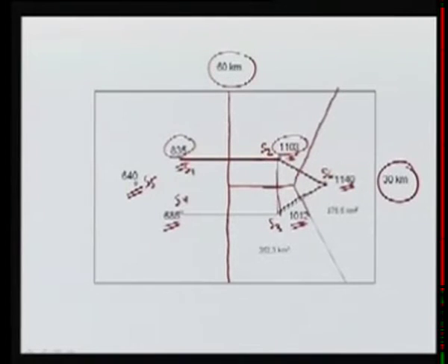Now once we do this, the effective area for the gauge S6 will be all this area, because in this area any point we take, suppose I take a point here, it will be closer to the gauge S6 than any other gauge. If I take a point exactly on this line, it would be equidistant from S6 and S2. So any point here or here or here would be closer to S6 than any other gauge.